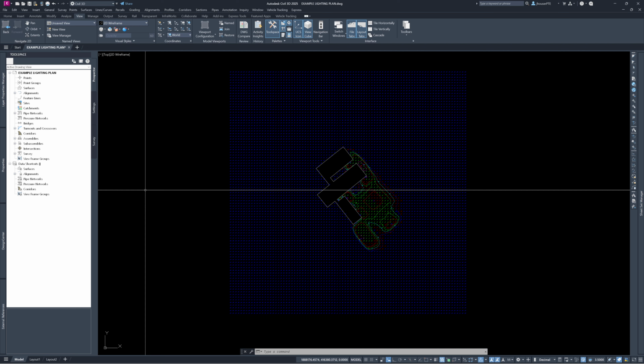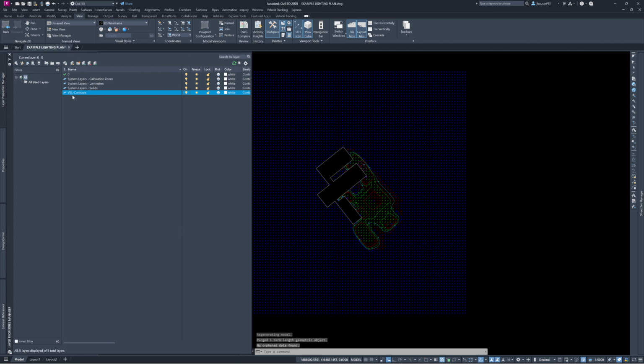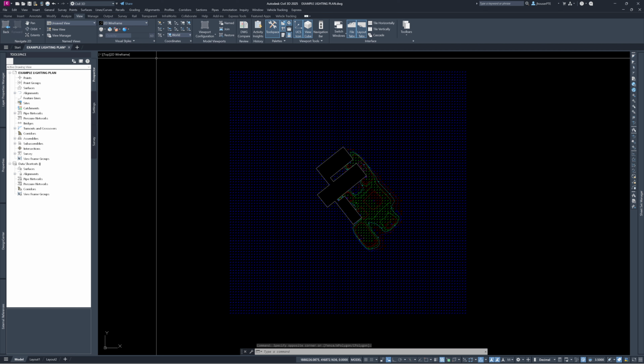Now we can see we're down to just several layers, but these aren't part of our normal layer standards except for the VSL's contours. I'm not sure how well this is going to work without having everything bursted, but in CAD, there's a Manage button, and then there's a Layer Translator. And I have gone through and I have created a Layer Translator that allows it to do a lot of the work I used to do by hand. So if you hit Load, it should go to, well, it did in my case because it's already there.